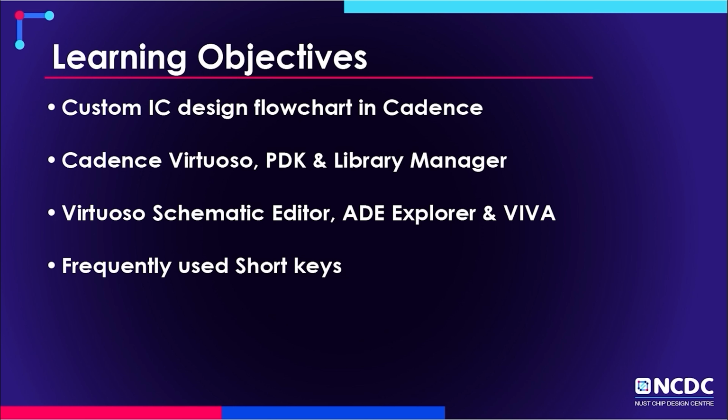Once the environment is set up, we will design the schematic of a CMOS inverter using the Virtuoso Schematic Editor and simulate the circuit using Analog Design Environment or ADE Explorer. After that we will analyze its waveforms in ViVA, which stands for Virtuoso Visualization and Analysis. Finally, I'll show you some frequently used shortcut keys in Cadence Virtuoso to improve your design productivity. I'll also attach a reference for these shortcuts at the end.